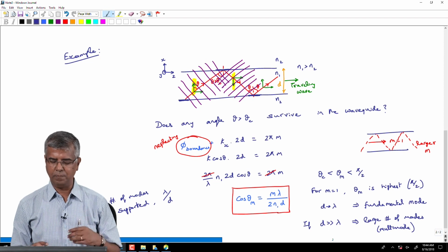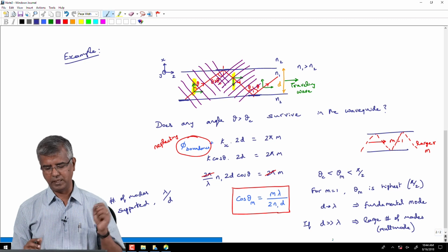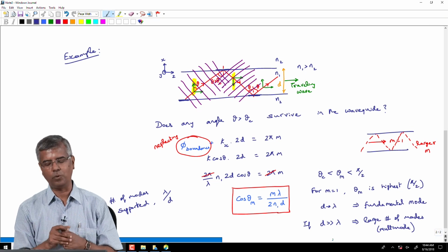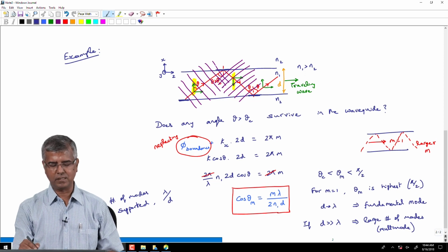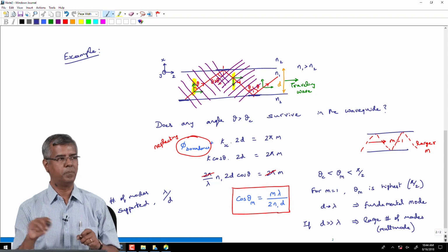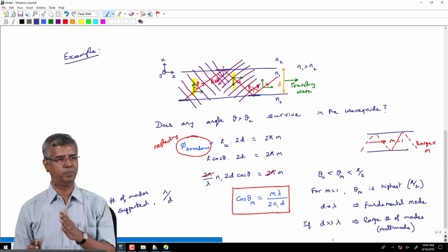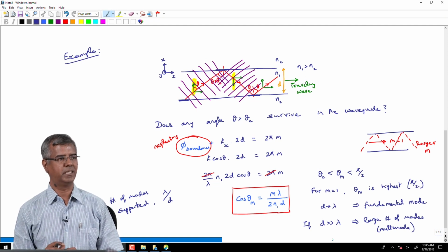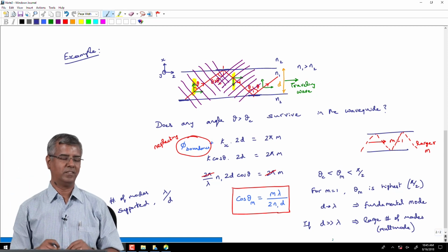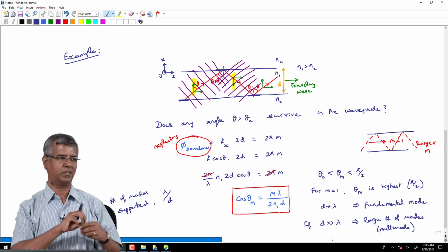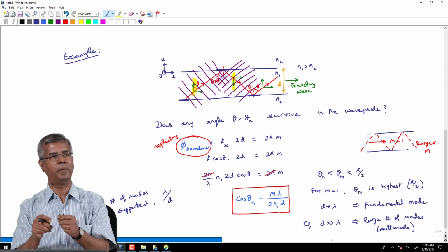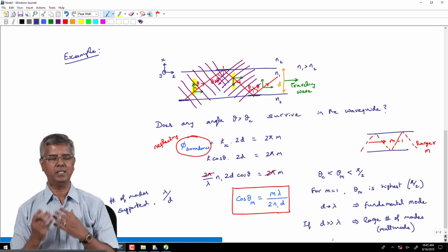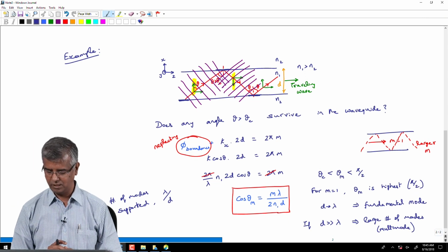So, for example, and this is something that we can probably demonstrate also, you send red light through a multimode waveguide and then you bend the waveguide, okay. If you bend the waveguide, what happens? You are essentially changing the total internal reflection condition at this point. So, when you bend the waveguide, some of those modes, the steepest modes that were guided in this waveguide, may not satisfy the total internal reflection condition. So, they will escape out. So, you will see red light. Normally, when you have a straight waveguide, you will not see any red light coming out because everything is actually guided within the structure. But the moment you bend it, where I am talking about a multimode waveguide, you will have some of these modes escape the waveguide and you can see that corresponding radiation, okay. So, we will try to demonstrate that later on today, okay.